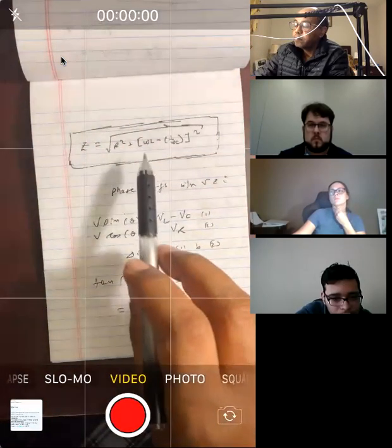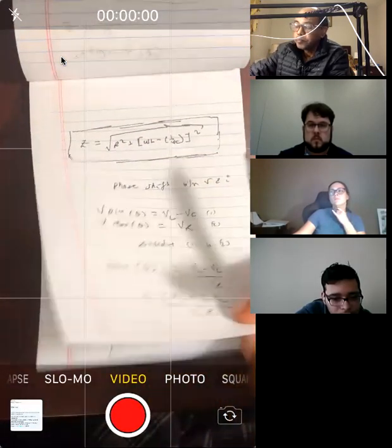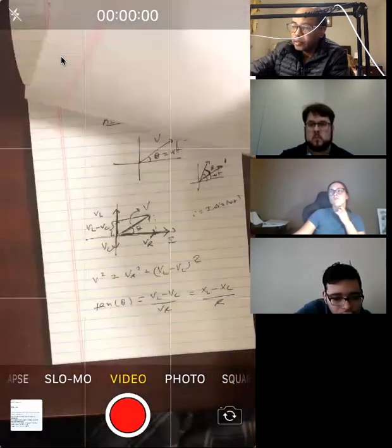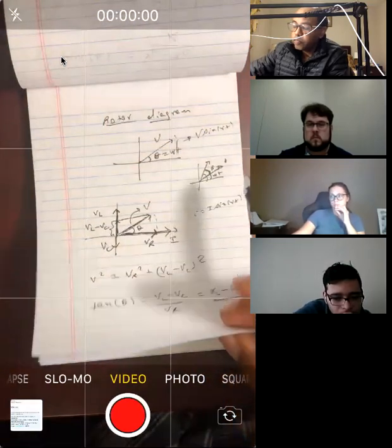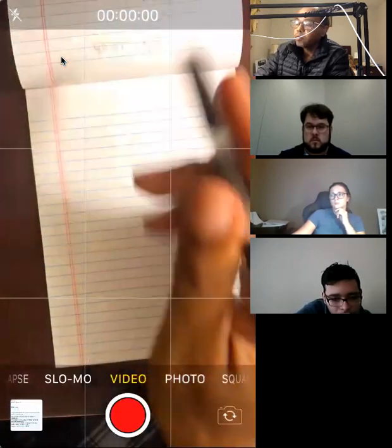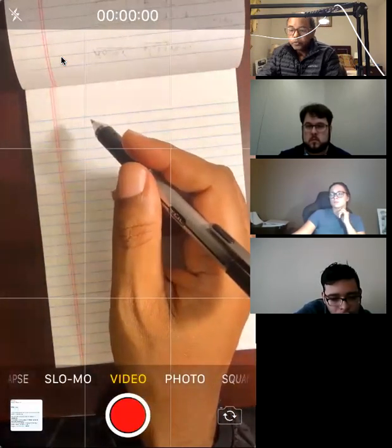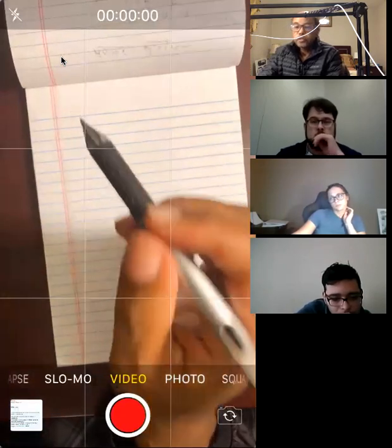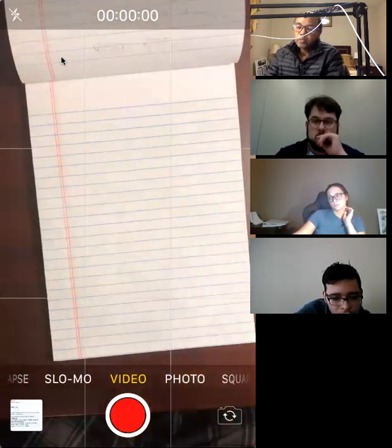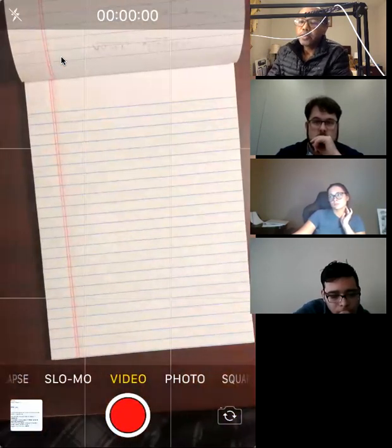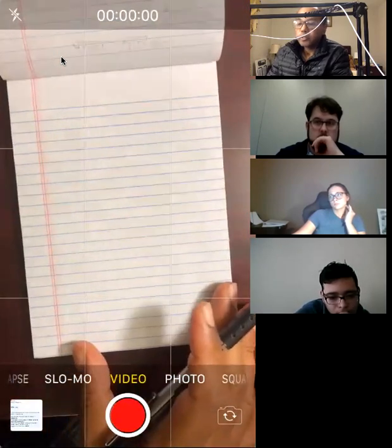Now, as you can see, the impedance of the circuit depends on the phase shift, on frequency. And so there is a special frequency that we call resonant frequency. So let's define what we call the resonant frequency, which plays an important role in tuning circuits of radios, television, and so on. Okay, you've got so many frequencies coming to your radio. How does the radio discriminate between all these frequencies and pick a certain frequency? Okay, so when you dial a radio, you just pick a certain frequency. Let's see how they do it.